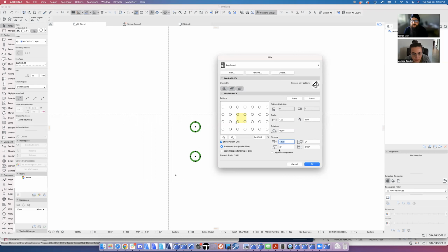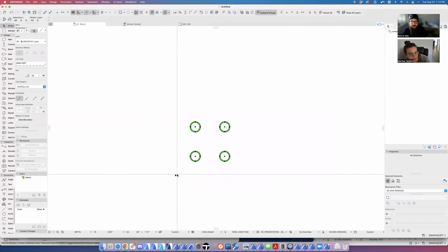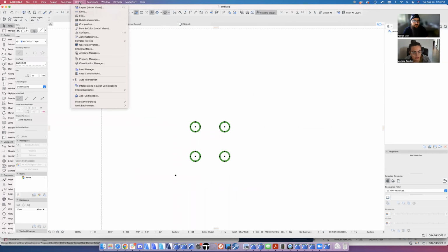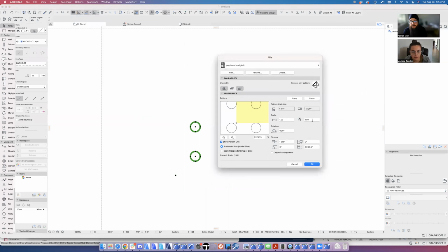Yes. Okay. Would you mind showing me quickly how, if you were to copy it with that spacer you created? Sure. So I would just select that as well, and we copy that, and that spacer I know is from this bottom down and this left over is just going to tile automatically from there, and then here. So that's basically the origin for this. So I copy all of that, and then I go to the fills, go new, symbol fill, and I'm just going to give that a different name, and then paste that in here.